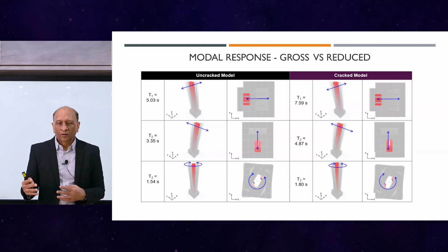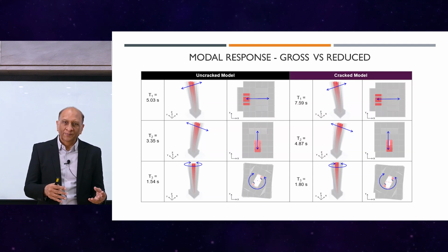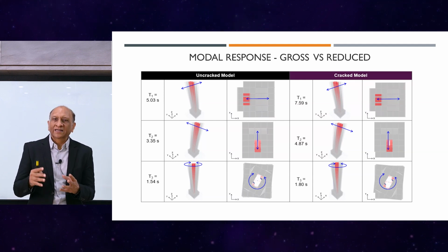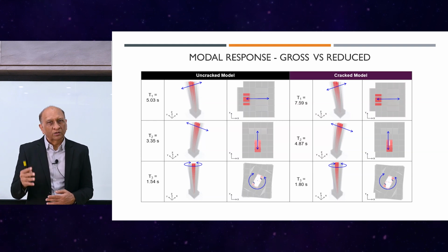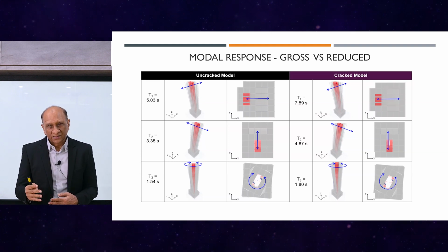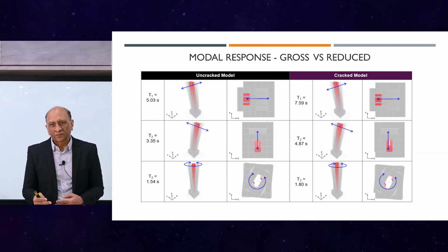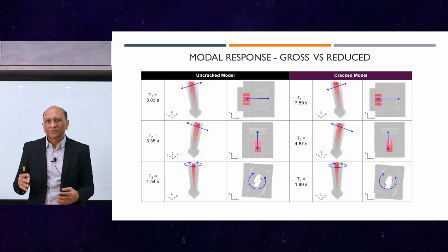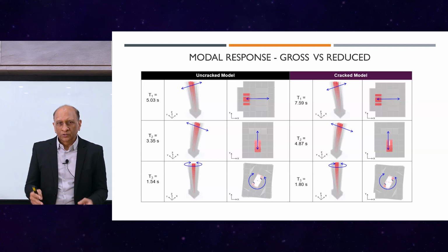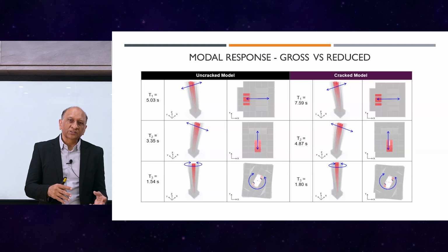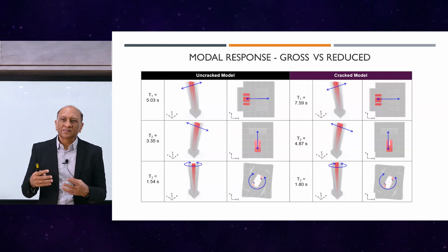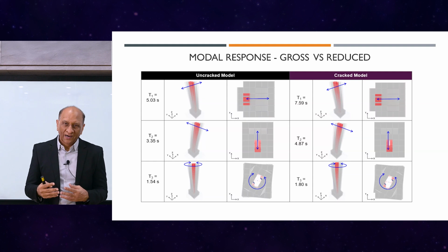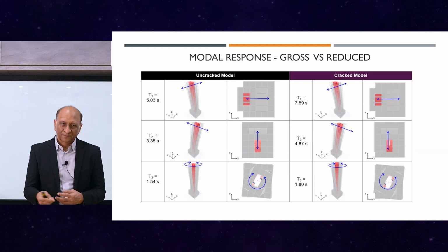Depending on how we look at it, it could be good or could be bad. But you will see later that 18% is not a big number because we're talking about an R reduction of almost 6, or even 8. So the stiffness reduction factors do affect, but their effect is not proportional to the R factor variation, although this is added on top of the R.